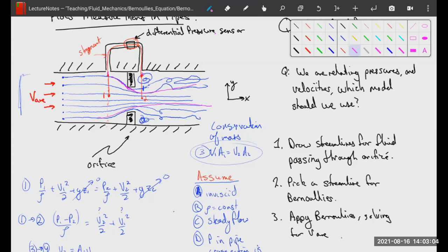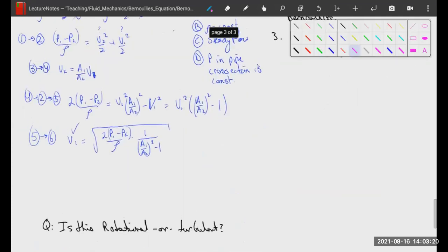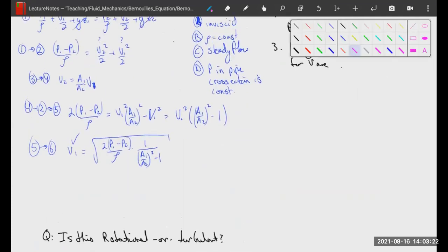In fact, I think the area becomes about half of the orifice area. But at lower Reynolds numbers, that's not true. It becomes somewhere between the orifice area and half, right? And in terms of vocab, how you would say this is that A1 over A2 is equal to a function of the Reynolds number.